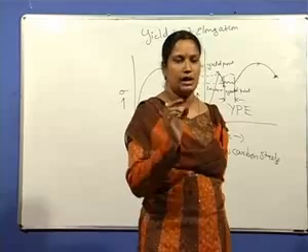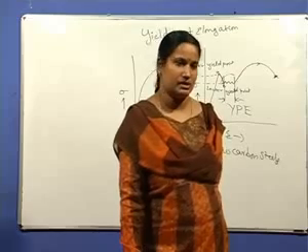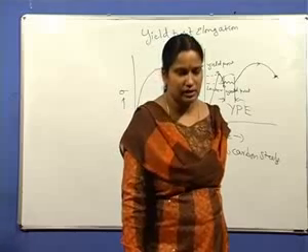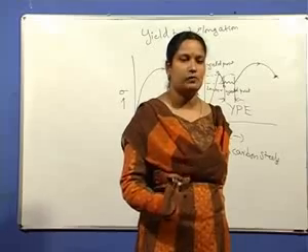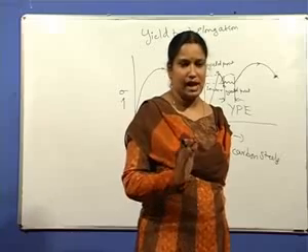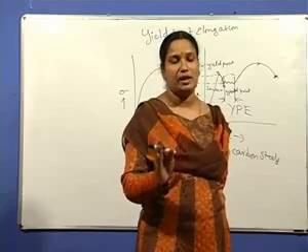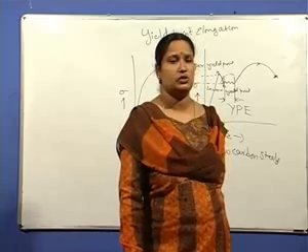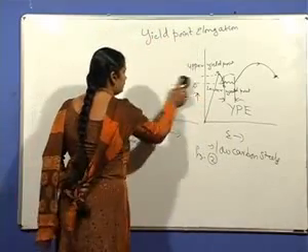Interstitial elements are carbon, boron, hydrogen and nitrogen. They occupy the interstitial sites. Whether interstitial or substitutional, they cause strengthening. The reason is that the difference in sizes of the solute and the solvent creates lattice strains. These lattice strains react with the stress fields of the dislocations and thereby strengthen the material. So this is solid solution strengthening. Now I'll draw a few figures of solid solution.